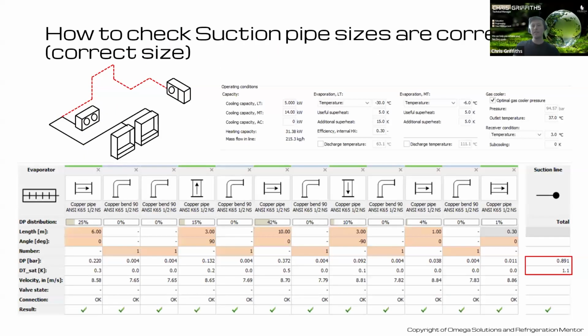What we'll do is break that section into various parts. We'll use Danfoss Cool Selector here. There are other software out there, for example, White Rose MicroPipe, which would do this much quicker. But Danfoss is free for people to use online, and it's fairly intuitive as well. So we'll break this red dotted section into its constituent components. We'll have our directional flow, whether it's horizontal, going upwards or downwards, and then the type of bend and how they fit together.